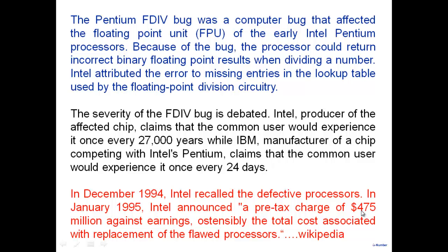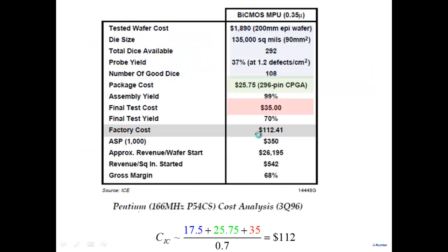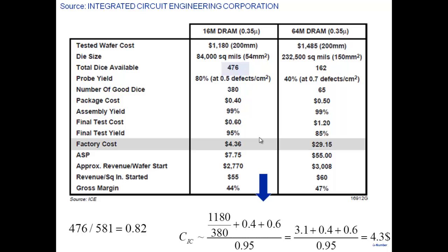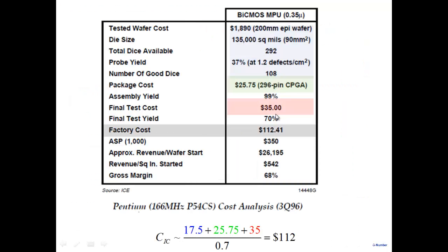All right, so you can imagine, you release an IC into the market, and there's a bug in it, there's an error in it, your whole reputation goes, you lose a lot of revenue here. Testing is extremely important. In fact, there's a whole area of digital design where they talk about design for testing. You deliberately design in such a way that subsequently it would be easy to test. And for that, you can add additional circuitry which makes testing easy.